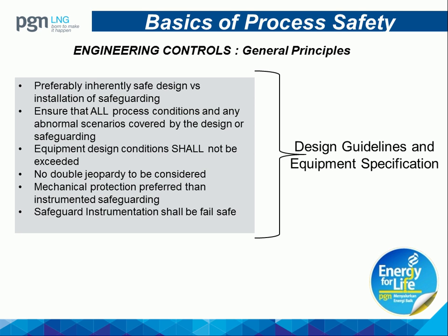And then the equipment design condition shall not be exceeded. This is very clear. But we also need to ensure that no double jeopardy is considered during design. So double jeopardy means that two independent incidents happen at the same time. That is very unlikely. Sorry.